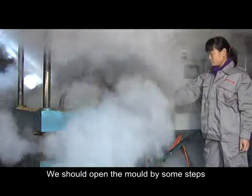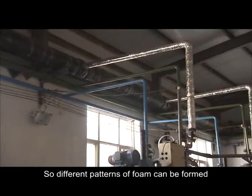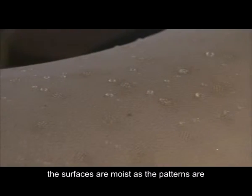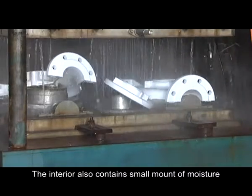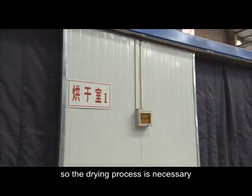We should open the mold by some steps, such as compressed air. At last, different patterns of foam can be formed. When the patterns are taken out of the mold, the surfaces are moist as the patterns are heated by steam and cooled by water. The interior also contains a small amount of moisture, so the drying process is necessary.